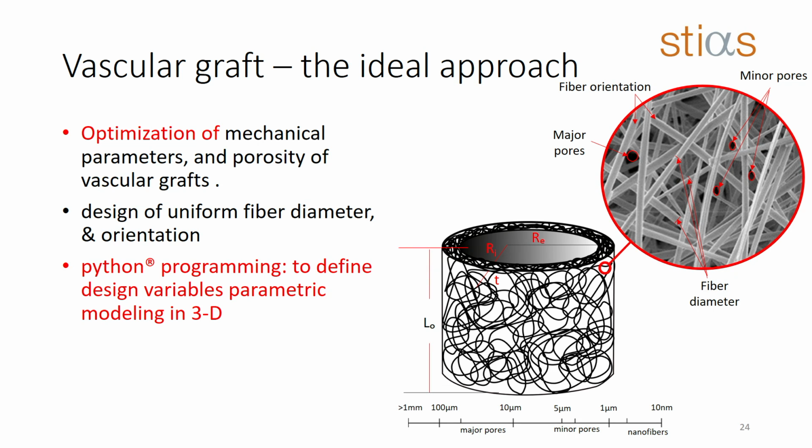Not only that, remember these are fibers at the nanoscale, as you can see from the scale at the bottom of that slide. So we are talking about nanofibers, fibers that are less than 10 nanometers, for example. Now, the only challenge that has always been there during the production of these structures is how to get a uniform distribution of these fibers. Remember, if you can get a uniform distribution, then you can actually predict their strength and their performance eventually.